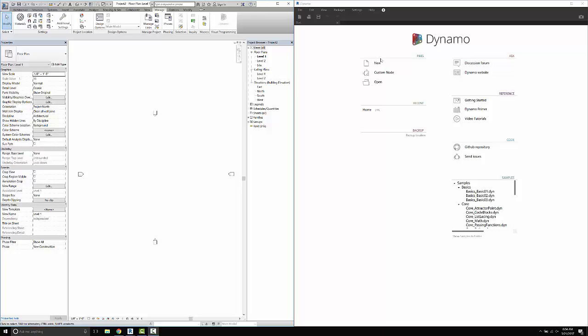So what we're going to do is create a conceptual mass, some mass floors in Revit, and think about those things as something that is parametrically linked between the levels that you created in the model as well as the geometry that you have, and then map some just basic information onto those mass floors so that you could start analyzing, say, the way that they're performing, either through daylight or views, say, out from the floors, which we'll try to cover in some future tutorials.